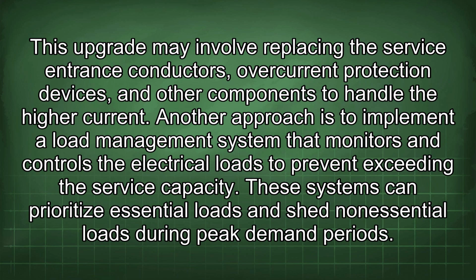This upgrade may involve replacing the service entrance conductors, overcurrent protection devices, and other components to handle the higher current. Another approach is to implement a load management system that monitors and controls the electrical loads to prevent exceeding the service capacity.